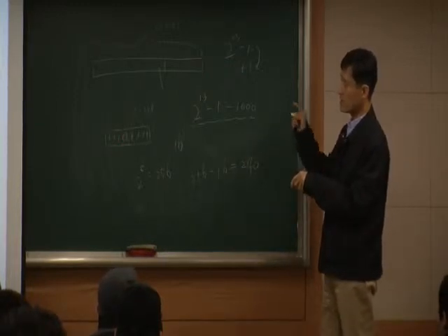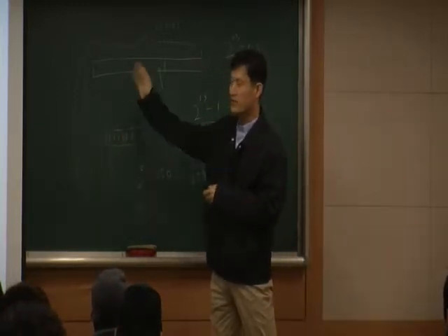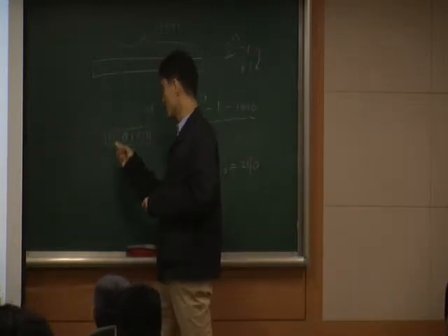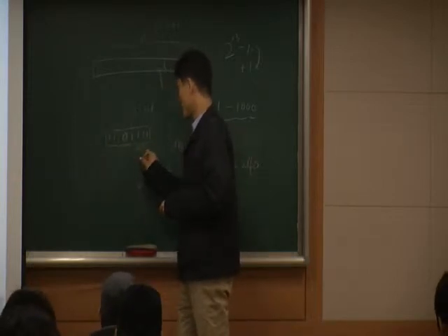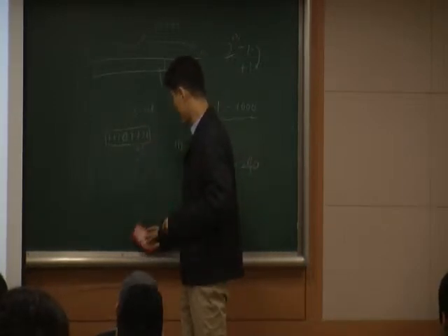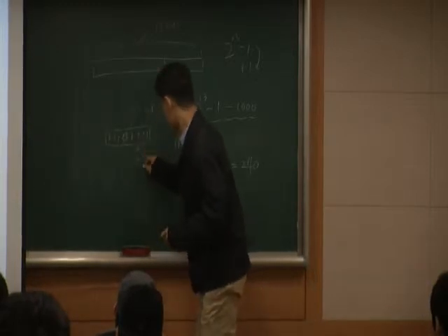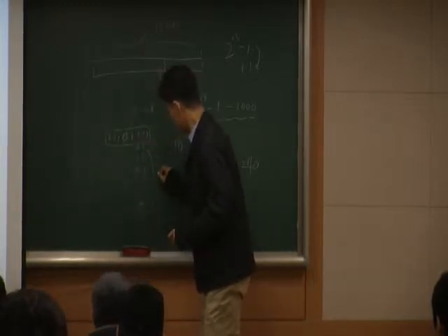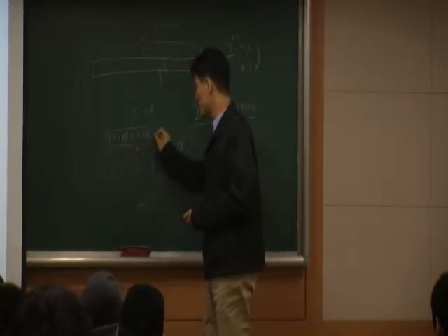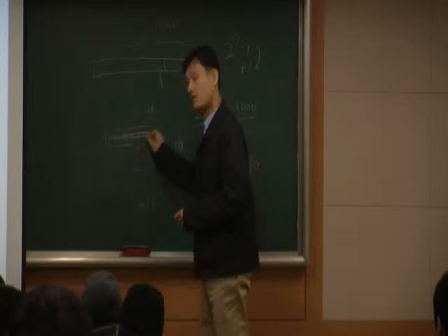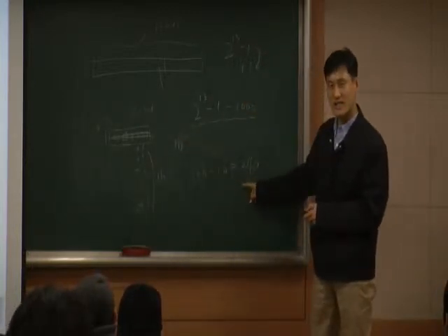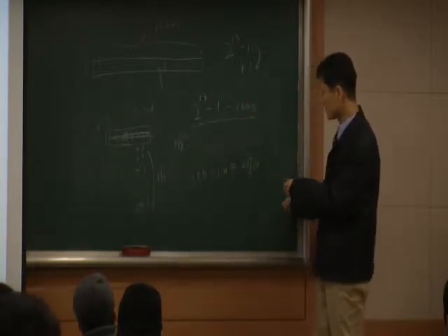When I set this as the initial value, now I want to run the timer. Then in the timer, we have a pulse. We have one pulse, then you're going to add it. One more pulse, you have added. So whenever you have pulses, the hardware will keep adding like this. And until you have 16 pulses coming in, now what happened? This one becomes all 0 and the carry happens at that time. Because that's how we designed it, right? We set the initial value 240.